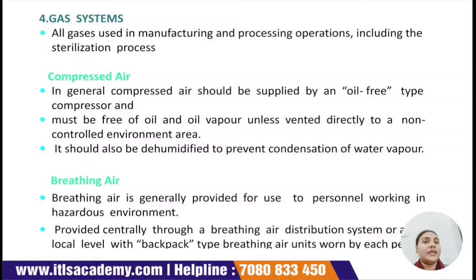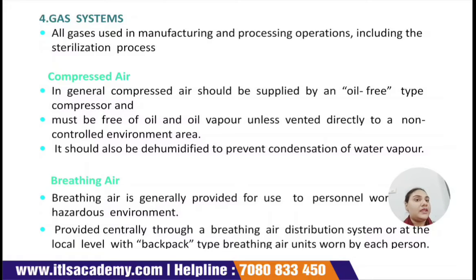Now comes the breathing air. Breathing air is generally provided for the personal use of those working in a hazardous environment. Whenever workers or employees work in an environment that is full of toxic substances, a personal breathing system is provided. So breathing air is generally provided for personal use, not for production use. It is provided centrally through a breathing air distribution system, or at the local level with a backpack type breathing air unit worn by each person.